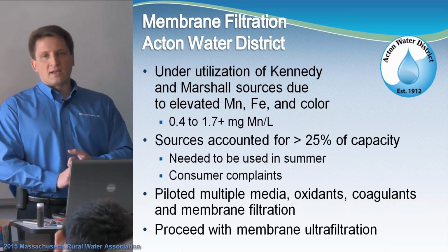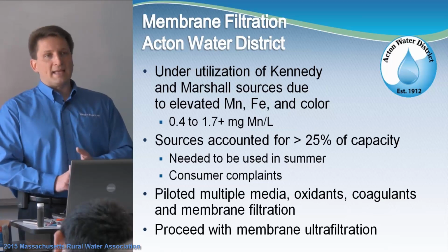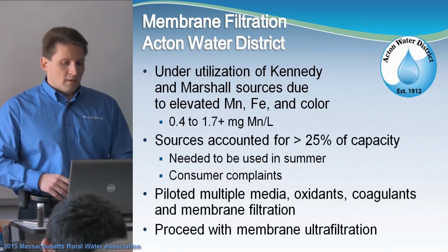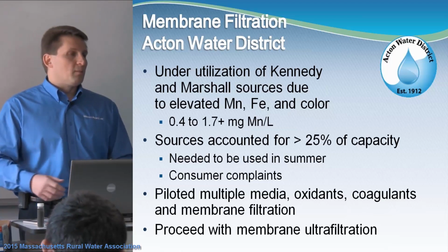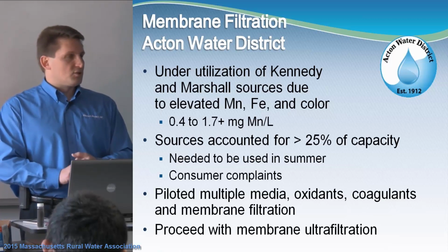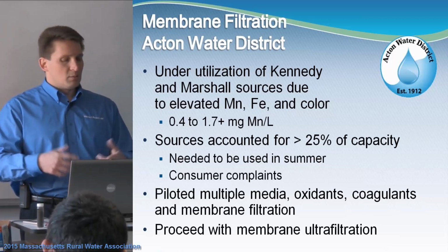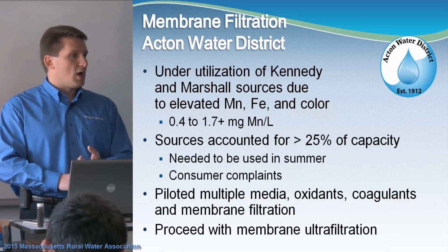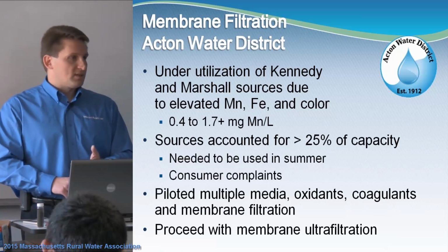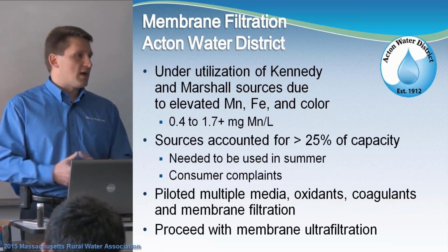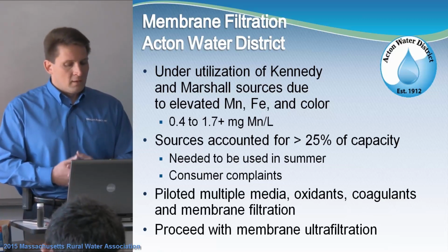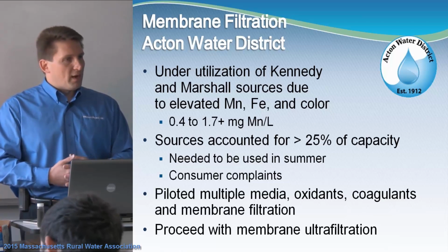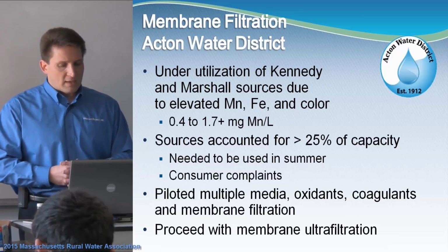We used various oxidants. We had to use coagulants to get the color out of there. And we also looked at membrane filtration. But because the media just really weren't working that well, similar to the rye example, the run times weren't long enough, the oxidation wasn't satisfactory enough so that the treatment could not get removed well enough. Then we transitioned into the membrane filtration process.